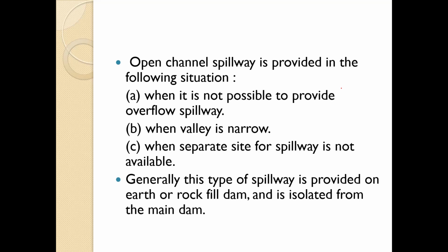Expansion joints are usually provided in the channel at intervals of 10 meters in either direction. The expansion joints should be made watertight so as to avoid any underseepage and its troublesome effects. Underdrains are also provided to drain the water which may seep through the bottom and the side walls. These underdrains may be in the form of perforated steel pipes, clay tiles, or rock-filled trenches. If the slope of this channel can conform to the available topography, the excavation will be minimum.